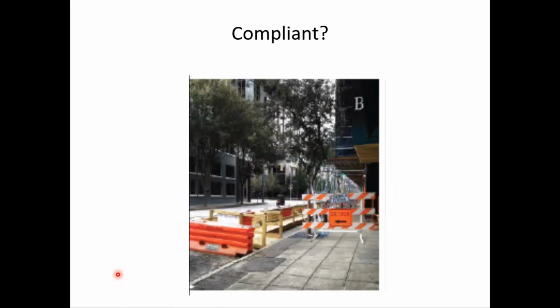So here's an example. Notice in this city, they are closing the sidewalk, it looks like for some building construction work. And they're detouring pedestrians, it looks like, into the street. And this is the device used to close the sidewalk, and the sign indicates detour. So it looks like a type 3 barricade as defined by part 6 of the MUTCD.